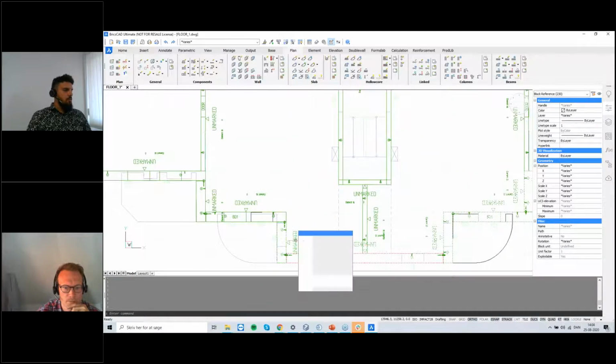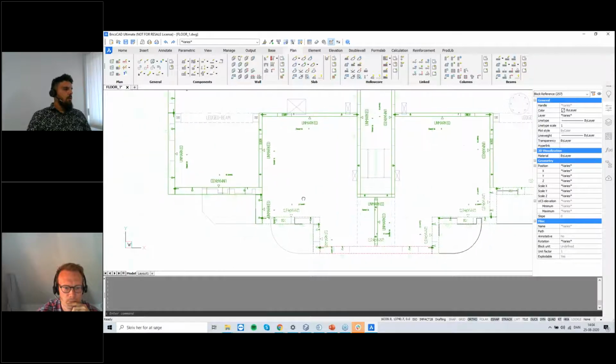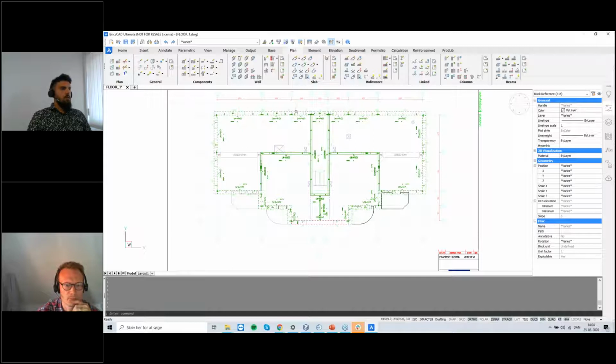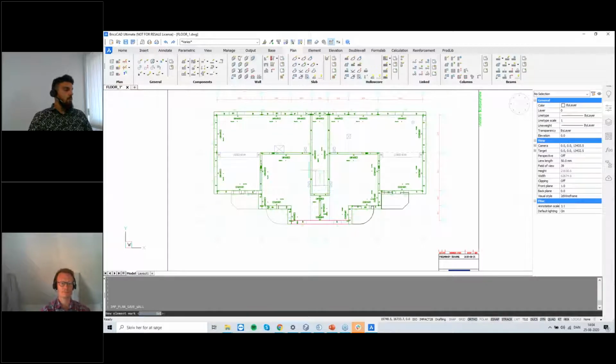If that's not what I want, then I can just select all of them together, and the software is going to give them a name by itself. But by doing that, I am also selecting them in the way that I want them to be erected. Actually, which gives my planner a heads up, and he can plan them for erection sequence according to the element mark instead of clicking it himself. Exactly. So I select my walls, very easy, save walls.